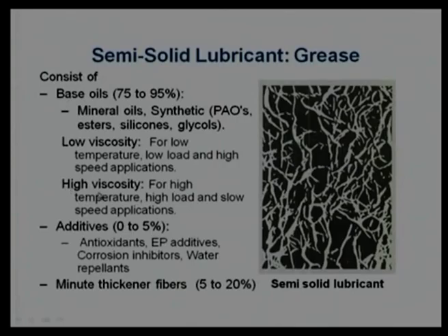While coming to the high viscosity, one application I mentioned is high temperature, the other application is high load. If the load is very high and we do not want the oil to be squeezed out from the interface, then we should use a high viscosity oil. And for high load with low speed operation, not high load and high speed operation, you need to use a good lubricant. Ordinary mineral oil or ordinary high viscous mineral oil cannot be used for this kind of application.